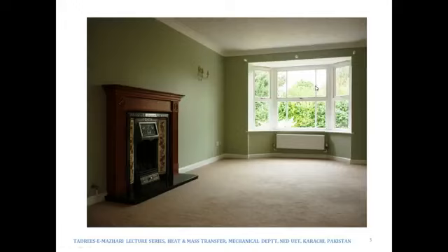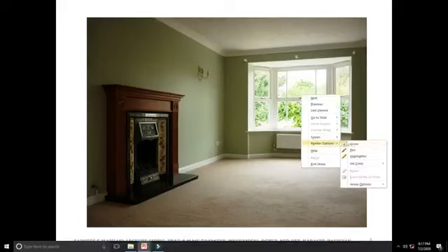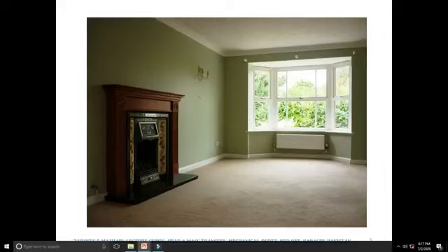See, if there are certain walls in this room, and let's say this is surface 1 and this is surface number 2, the floor is surface 2, and we are interested in finding out the heat transfer due to radiation between surfaces 1 and 2, then it cannot simply be sigma epsilon A (T1^4 minus T2^4).